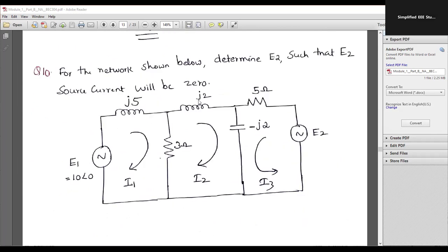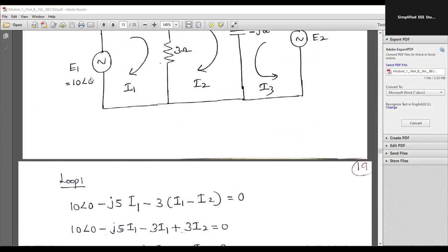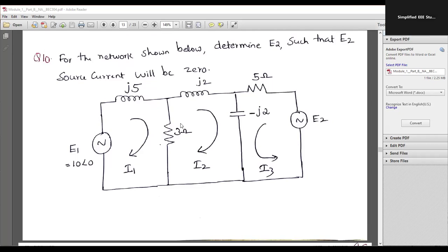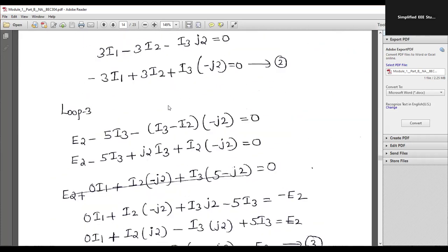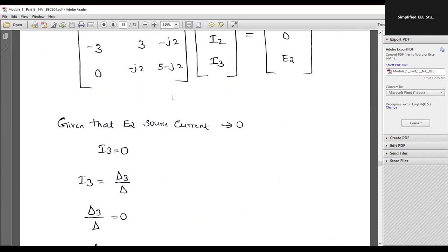Don't worry. In AC circuits also you should be able to solve problems. In that you should know about complex numbers, then only you can solve the reactance. Whenever it comes to AC, we should consider impedance, resistance and reactance. That means Z is equal to R plus jX, so complex numbers come into the picture. For addition and subtraction, you should make it into rectangular form only. For multiplication and division, you should convert into polar form. That point you have to remember.